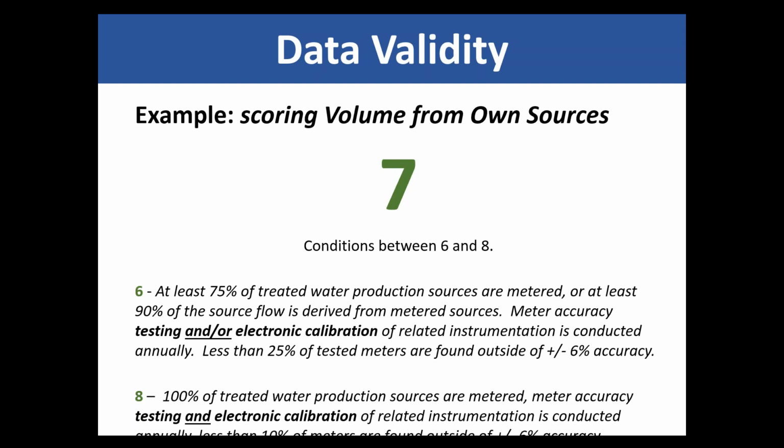water audit software. So you'll have to also think about, when you come up with an operating budget, is it reviewed by a CPA? Is it comprehensive? Does it include sewer costs that you had to pull out? Those sorts of questions. When you talk about pressure, how many pressure zones are you operating? Are they discrete? Do you log pressure? Do you work with a hydraulic model? These are the sorts of questions that you'll want to engage with your colleagues.